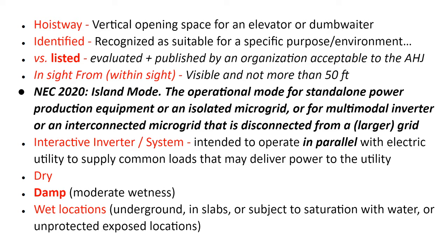Being able to tell the jurisdiction if it's an islanding inverter or an interactive inverter is something they might need a little bit of education on, because they're thinking anti-islanding. An islanding inverter is all right, but it has to be truly isolated, truly islanded. You can't have an islanded inverter that is still connected interactive to the grid, because if the grid's down, first off, your inverter is going to output all of its maximum power directly into the ground. And if that ground is where utility linemen are working because it's a downed power line, you could kill them.